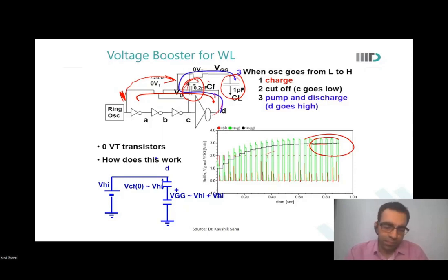But even equalization from let us say VDD by 2 minus 40 millivolts and VDD by 2 plus 40 millivolts to almost VDD by 2 on both the bit lines, means that you are transferring information across a pass gate.